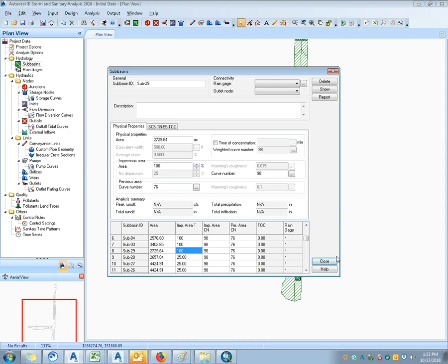One thing to look at on that, Paul, while you're checking: HydroCAD has done a pretty good direct link to AutoCAD now. I don't know if that might be a tool we could use to dynamically update in CAD, run it out so all the land use is added, and then somehow put it back out so we can pull it into SSA. It might be an extra step, but it provides a dynamic link that's tied to the hydrology.